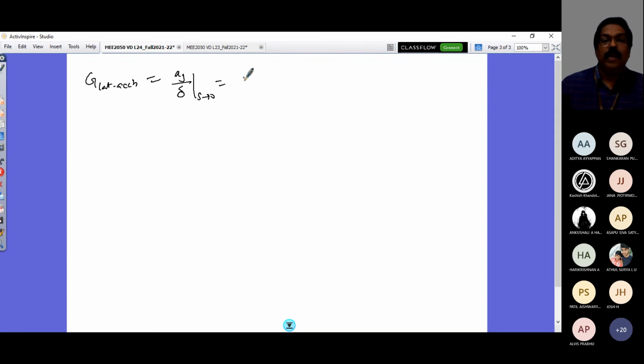So that's going to be Ay. Since it is steady state motion, this Ay is given by u squared by R by delta. So u squared by R by delta, I can rewrite it this way. So u by R is, R is equal to u by capital R. So u by capital R is r. So it's r into u by delta. So r by delta is the yaw velocity gain. I have to multiply that by u.